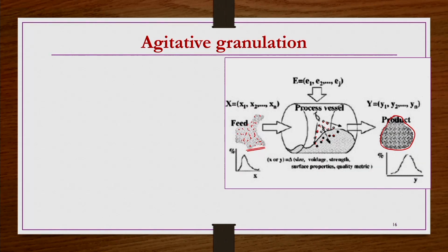If you see, the size of each particle in the feed is very small. The feed is not one single particle shown here; it has so many fine particles, as dotted particles like this here. When you do the agglomeration, they all form lumps, agglomerates, because of the agitation, and then this particle is in a better size to handle in a subsequent transport operation.